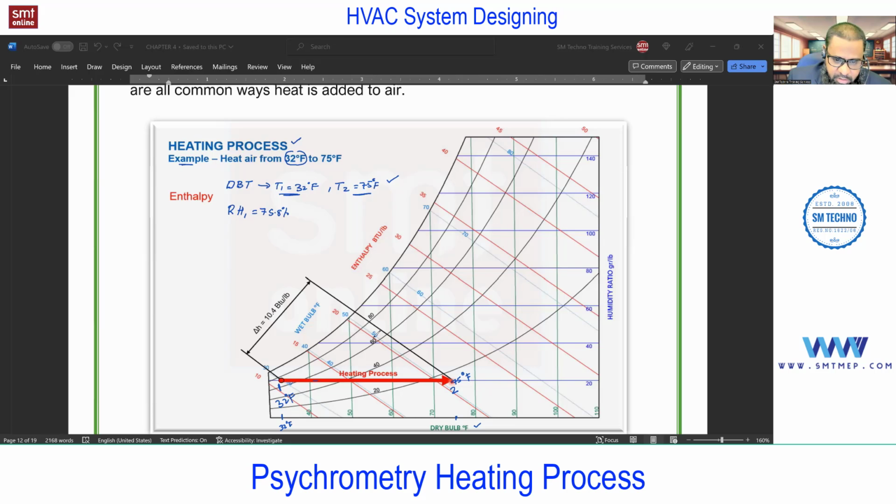You see this is 60, no? And this is 80, and if I draw the point, it is very close to the center line of this, which is 75, and this is slightly above 75, so I'm considering 75.8. Or using these two parameters, you can find out with the psychrometric software also. The other parameters you can verify later. At this level, just focus on the heating process. The values I'm writing are extracted from that psychrometric software only.